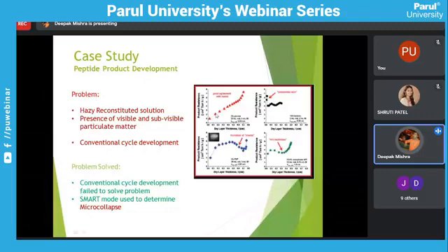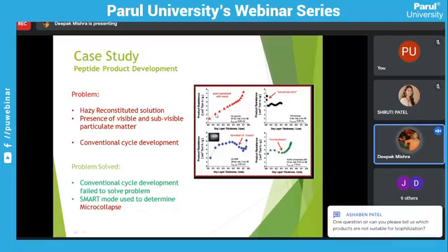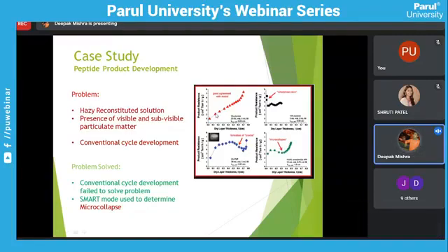Actually, I don't have the picture right now. Amorphous skin forms above the drug product as a screen layer, just like you can see on any tablet skin. So if your product has amorphous skin, this type of graph will show, based on dry layer thickness and product resistance.